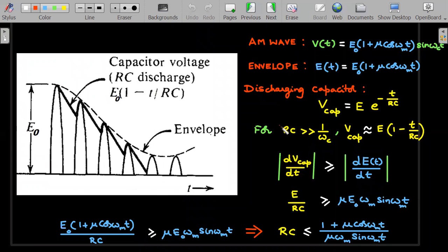So, a lot of things on the board. Just follow my lead. It is going to be a fun ride for people who understand this. Look at this one. I've enlarged that part where your discharging takes place. Remember, once the peak is hit, the RC circuit is going to discharge. Actually, this line is supposed to be an exponential curve like this, but we can make some assumptions here by assuming it's a straight line.